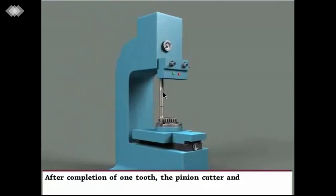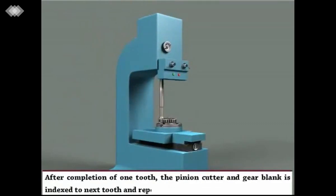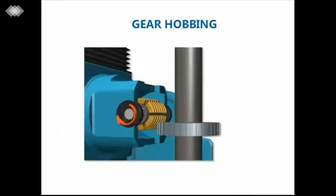After completion of cutting of one tooth, the pinion cutter and the gear blank are indexed to the next tooth using the indexing mechanism on the rotary table, and the same is repeated for the remaining teeth.